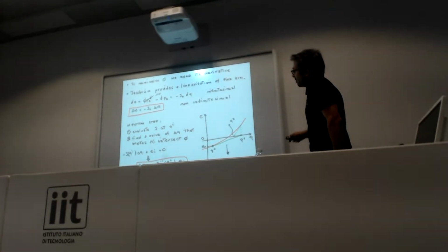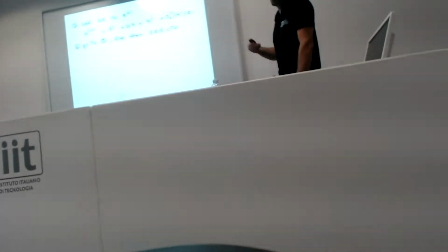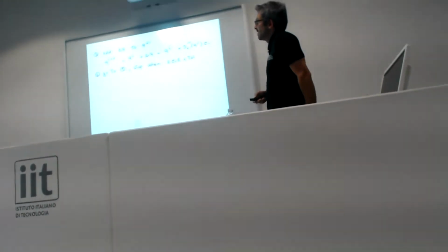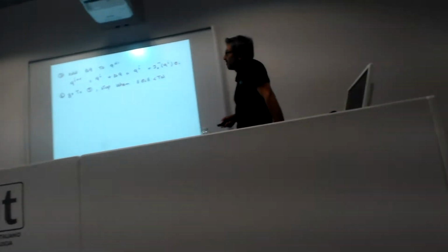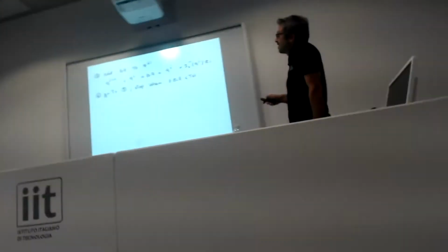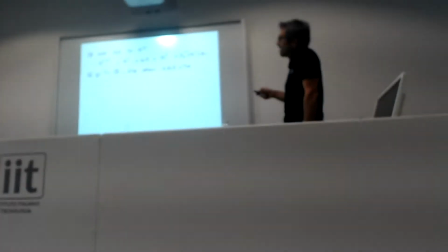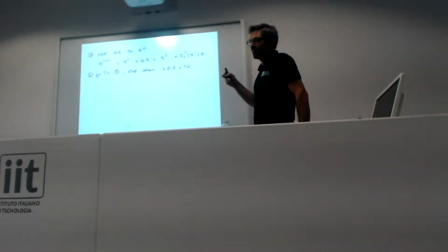So we move here, we move here, and this will gradually converge to the value we are looking for, the joint configuration that we are looking for. We want to stop whenever the error norm is below a certain tolerance. Otherwise, we iterate.